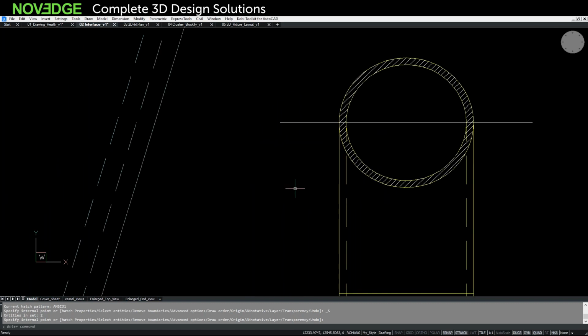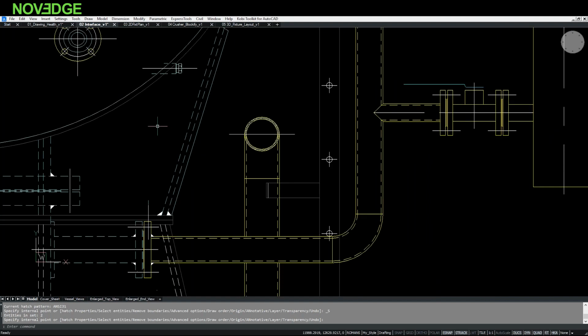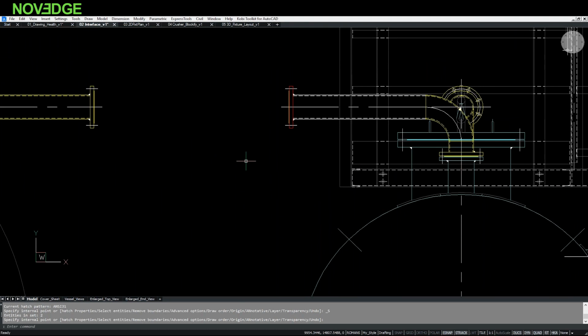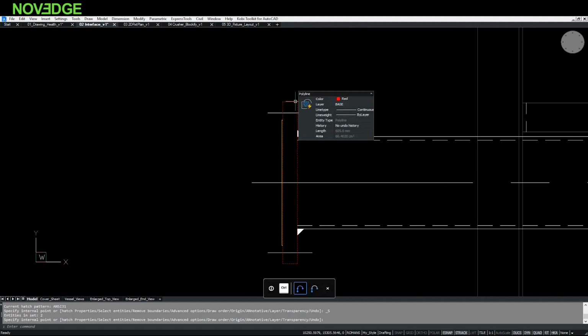In conjunction with the quad cursor, we have another tool called Rollover Tips. So I'll turn that on here. What the rollover tips allow you to do is this: if you've ever had a drawing where you need to quickly change a layer or color of an object, the conventional method requires several mouse clicks and searching for commands, and it takes a bit more time. With the rollover tips, as the name implies, I can roll over this entity and I'm presented with information about that entity.